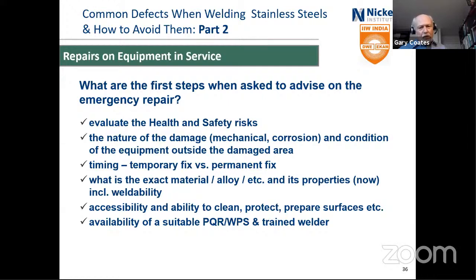And then, of course, suitability, if it's a pressure vessel, especially, or pressure pipe, of the PQR, WPS, and the trained welder. And sometimes if the failure occurs on a night shift, and you have to do a temporary fix, well, of course, you don't have all the good welders on staff there. So you really want to make sure you have somebody who knows what he's doing.